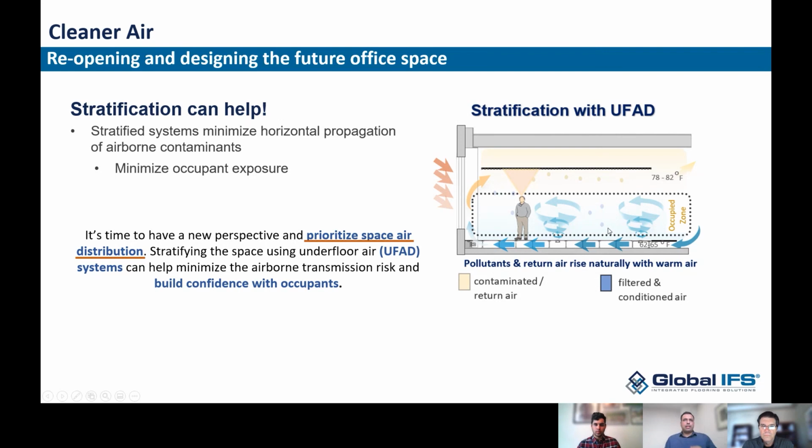Yeah, that's a good question, Chris. If you think about some of the active technologies that help you scrub the air, not just in your duct system, not just in your air handling system, but actually in the space itself, for example, bipolar ionization, where you're able to introduce ions in the space and actually clean and purify the occupied space. I think that's where underfloor air systems can really help, because those ions have a shelf life, right? They don't last forever. The more they have to go through, the quicker they get consumed, and they're not able to get to the occupant that they need to get to.